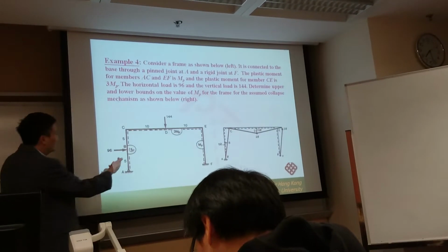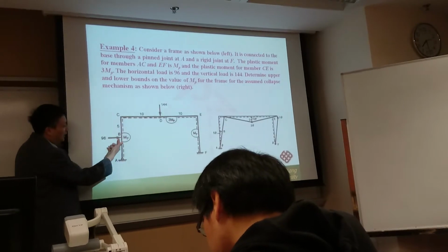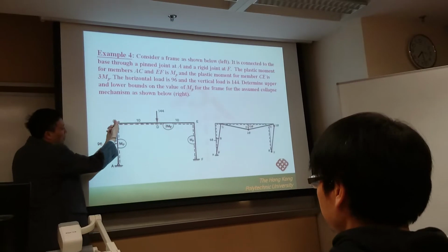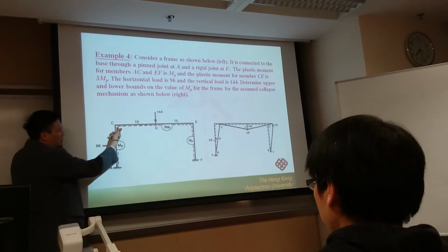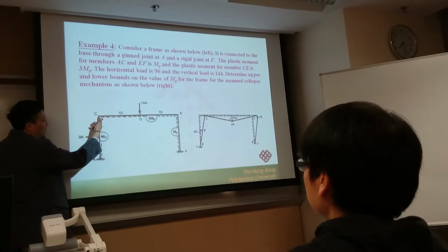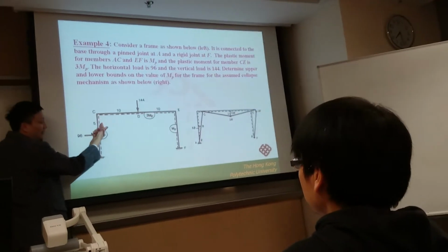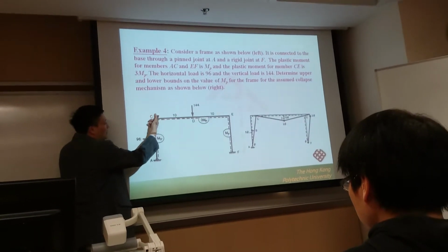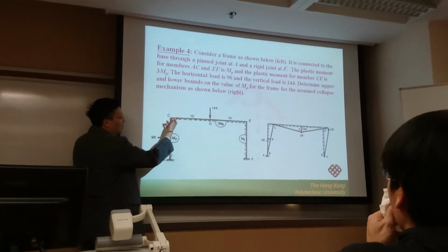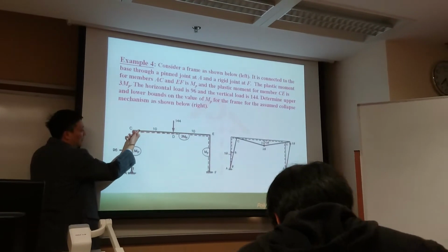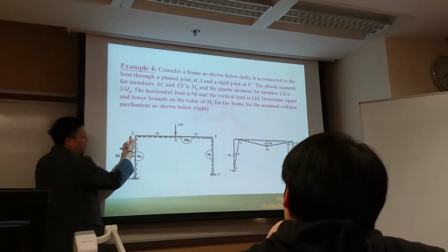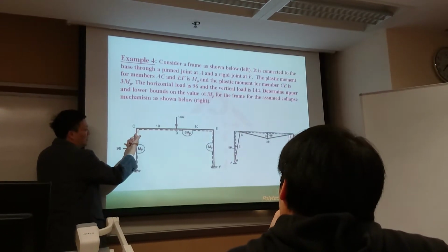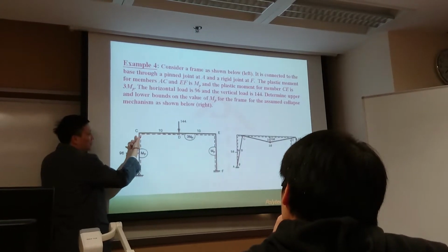When we do the moment check for section B, we have to make a rotation about section B, because we already obtained the moment for section C. So the rigid connection at section C can be replaced by a hinge and the calculated MC value. After obtaining the moment for this section, it can be replaced by one hinge and the real moment.